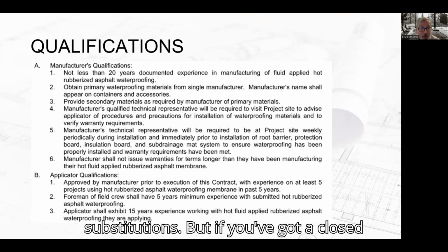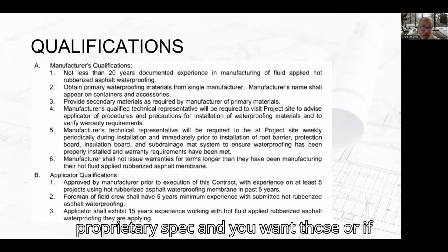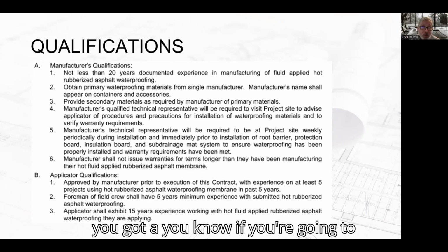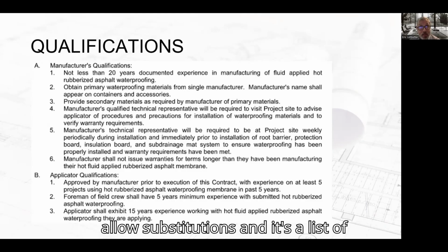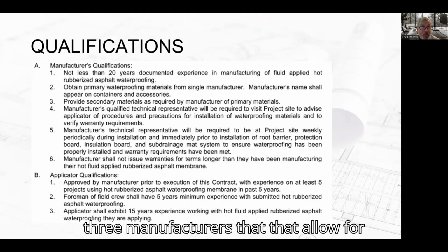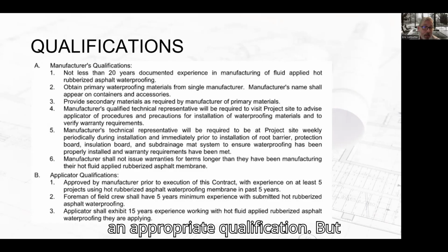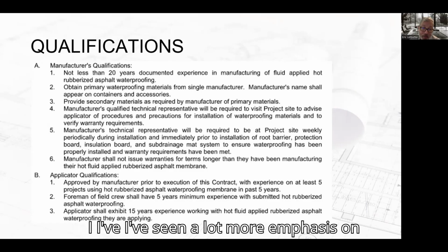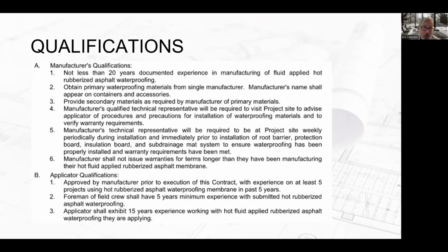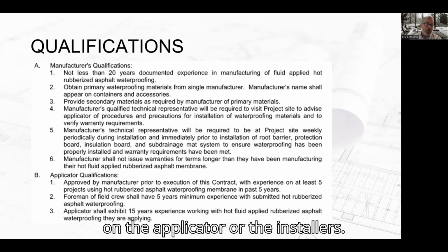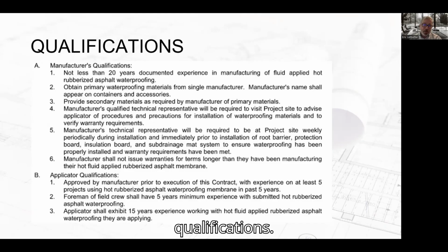If someone is allowed to do substitutions and you want that, then maybe those manufacturer qualifications are relevant relative to those substitutions. But if you've got a closed proprietary spec, or if you're going to allow substitutions and it's a list of three manufacturers that allow for substitutions, then maybe that's an appropriate qualification. But I've seen a lot more emphasis on the applicator or the installer's qualifications.